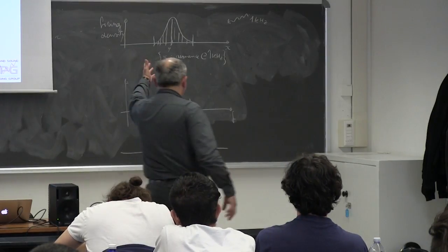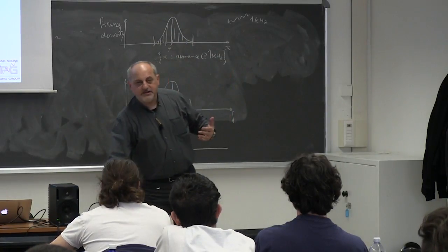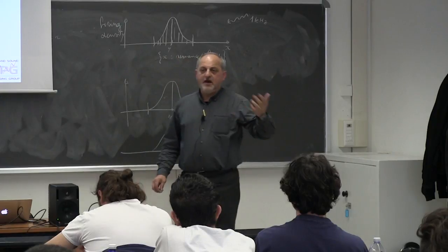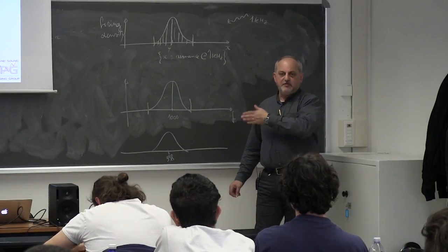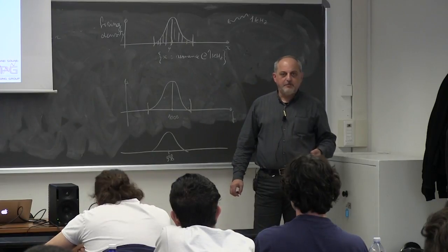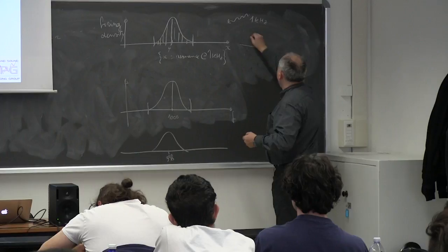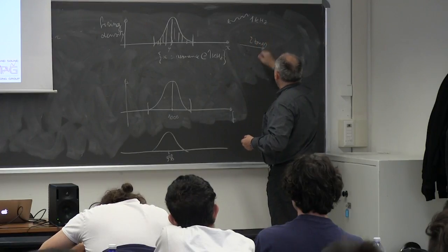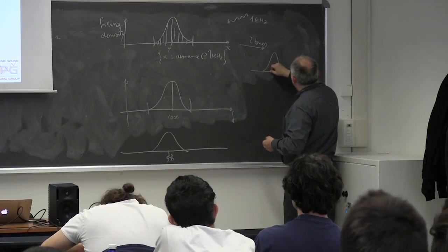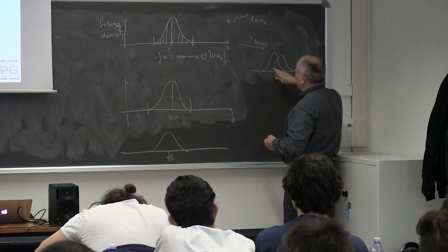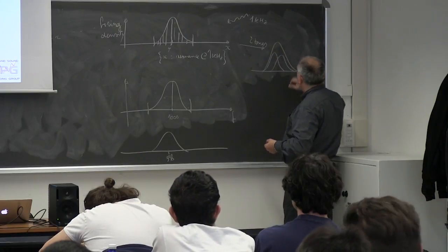It's pretty easy to find out at what frequency the pure tone is, because you just have to look for the maximum of that shape. But when there are two tones, what happens? The same diagram with two tones will look like this: a superposition of two of these shapes, so the result could be like this.